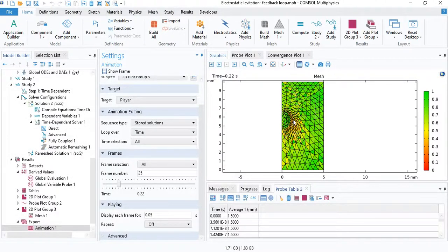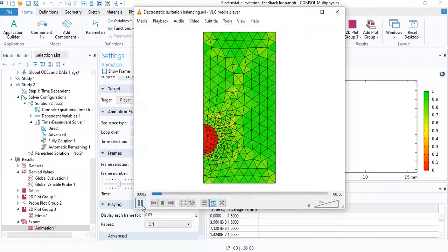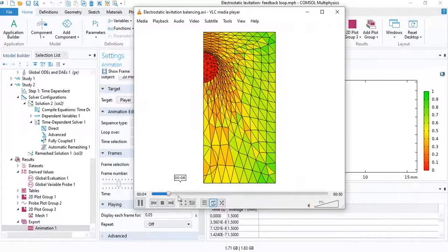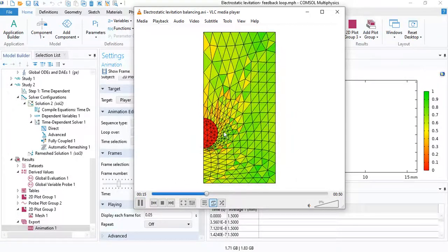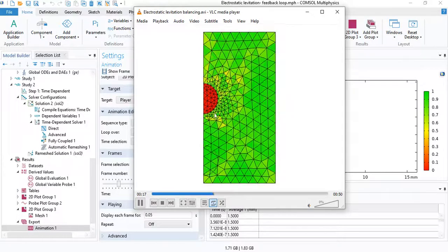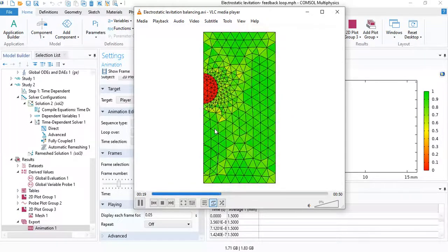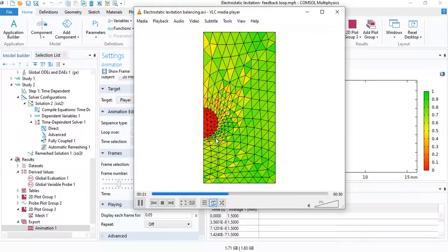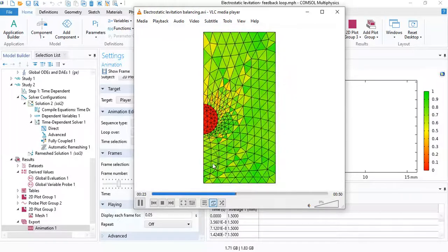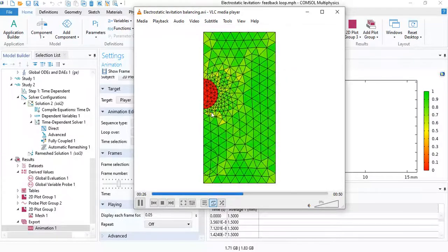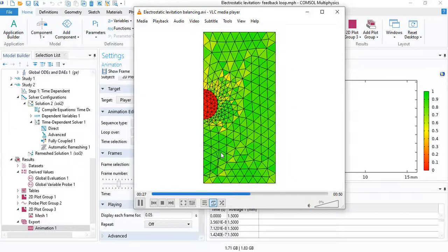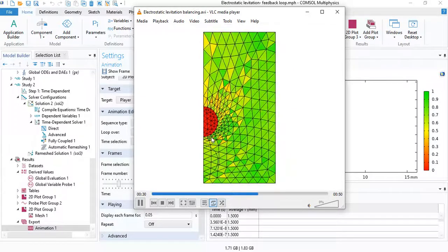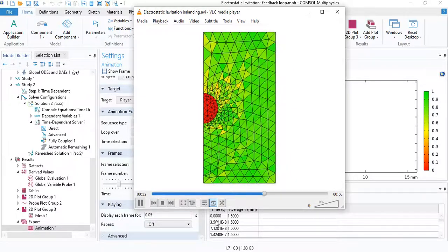All right, so now we can compare how the position of the sphere varies relative to what I showed you at the beginning of this video. In this video, you can see that the oscillations decay very slowly. I purposely did that because I did not select a proper value for the derivative gain. So the sphere keeps oscillating for a very long time, and in real applications, this is very undesirable.